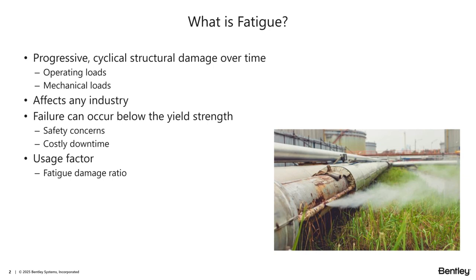Parts subjected to these types of cyclic loads are likely to fail even when the loading is much less than the documented yield strength of the material. A carbon steel pipe with a yield of 35,000 psi can still fail when the peak fatigue stress range is even 20,000 psi. Stress fractures can happen suddenly, even when the pipe in operation continues to appear elastic.